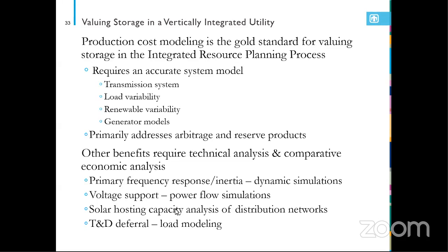But it can be a complicated process to pull all this data together. Other benefits require technical analysis and then comparative economic analysis. So if you're looking at primary frequency response and inertia, you have to do dynamic simulations. If you're doing voltage support, you have to do power flow simulations.